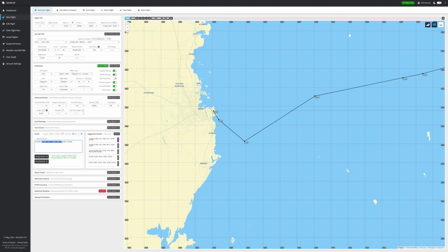Now, in between are your waypoints and airways. Anything coming in alphabet value is the waypoint. So LSIM, ITBUL, these are the waypoints. As you can see, these points are coming. And then if anything coming in alphanumeric value is an airway, L305, M677, these are all the airways.